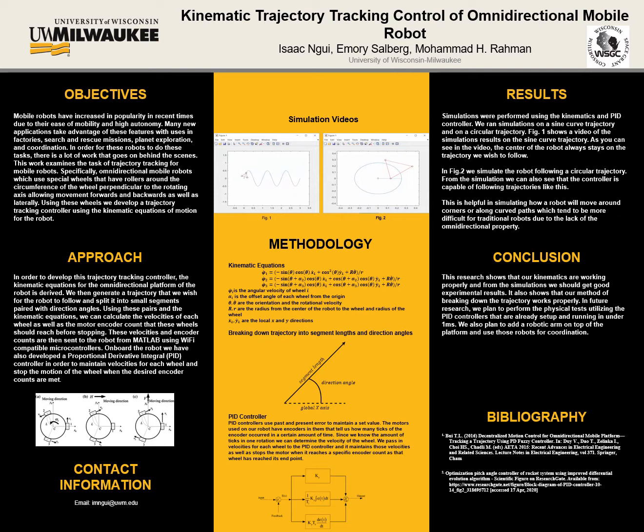and then while it's actually moving at that velocity, we will be counting all of the counts until we reach a certain desired count, and that count is basically from the kinematics we're able to calculate the exact position that our motors should be in, where the wheels should be. And so using that calculation, we're actually able to find the exact number of encoder counts that should have passed by when we get to that point. And so we stop our motors when we get to those points.